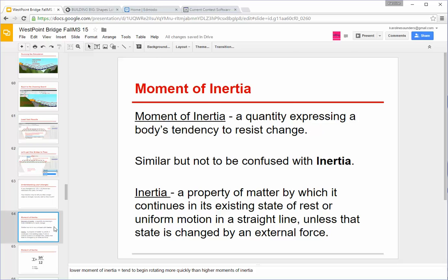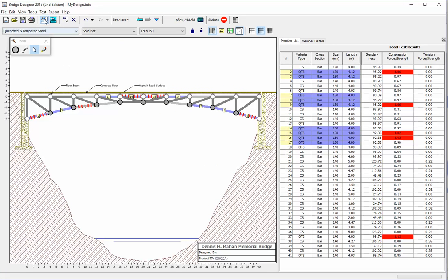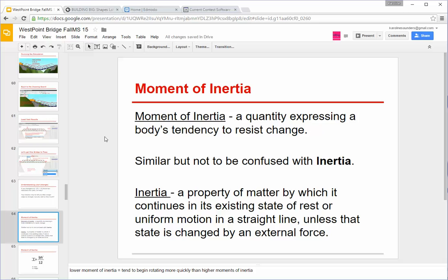So this is because, how do I run the simulation? You click on this sort of turquoise icon on the top left. And to get out of the simulation, click the button to the left of it. So this is because of the object's moment of inertia. And hang on, I see a question. Your bridge has to be stable to do that, correct? Yes. If your bridge is not stable and you try to run your simulation, it'll give you that unstable error.